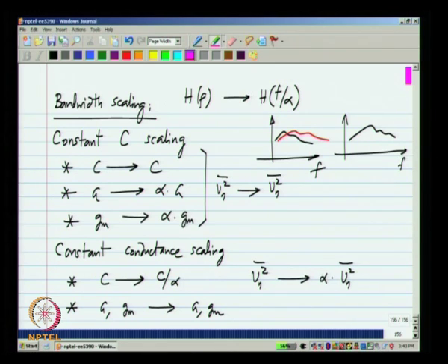That is a summary of systematically scaling noise in a given circuit, depending on whether you want to preserve the functionality or you want to scale the bandwidth without changing the shape. And you will have to do this very frequently when you come to circuit design, especially impedance scaling, because the first circuit that you realize may not be suitable for noise or power dissipation. In either of these two cases, you can alter the circuit without changing its functionality, usually to reduce the power dissipation or to reduce the noise.